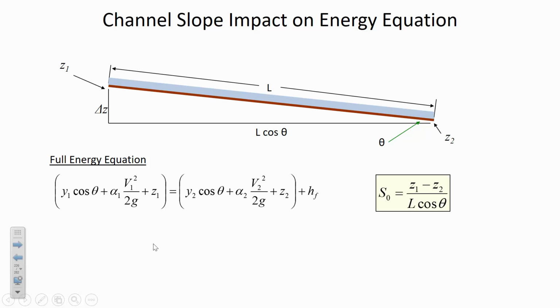And that is, there's going to be a small angle if it's an inclined channel here. And the length of the channel segment is going to be less than the plan view length if we're looking down from above. So you'll notice here this is going to be longer. So L, the hypotenuse of that triangle, is longer than the top view that we would measure on a map.